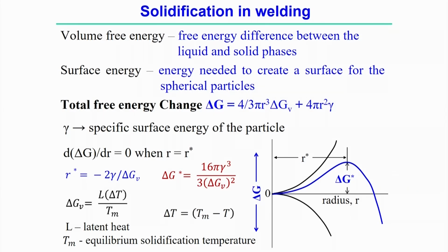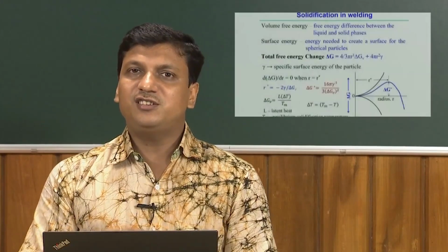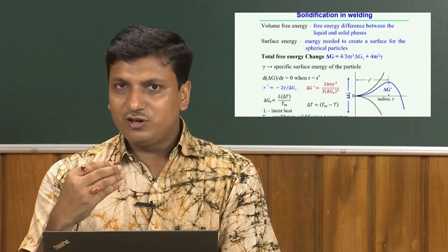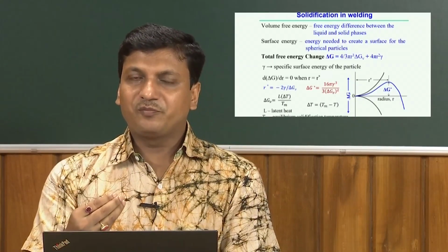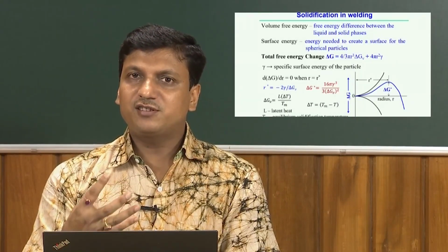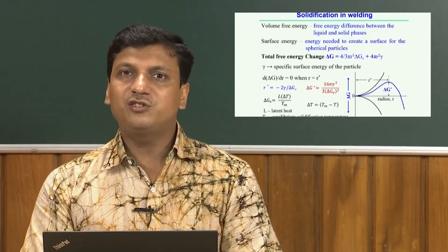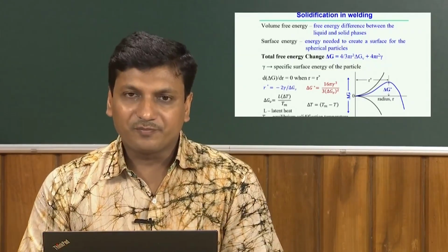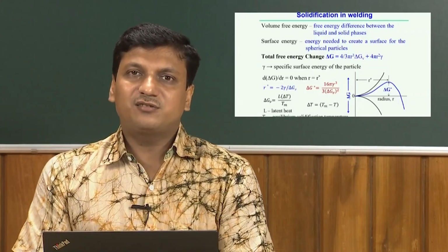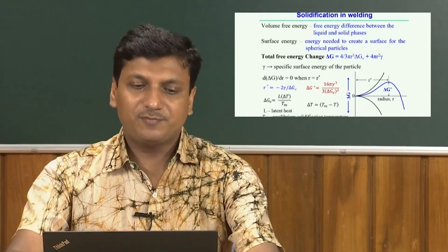Now, if we define the volume free energy, that is the free energy difference between the liquid and solid phases, because during the solidification process there is a change of the liquid to the solid phase. During this change of phase, some amount of volumetric energy is required to change from liquid to solid. That can be defined as the volume free energy.